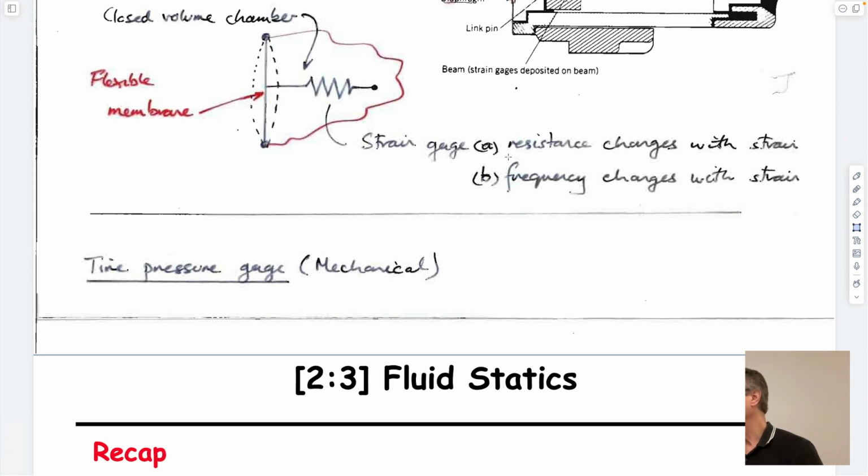Tire gauges, it blows something up past the little stalk. And so it's a balance between the pressure acting at the bottom of that stalk and the pressure moving and the fluid moving around it that gives the height rise in the pressure gauge, if you've used a mechanical pressure gauge. And of course, PZTs these days, piezoelectric transducers, merely take a crystal piece of silicon, you squeeze that silicon, you get a little electric voltage out of it as you squeeze it. If you measure that voltage, that gives you the pressure that's applied on it. So that's what most of them are these days.